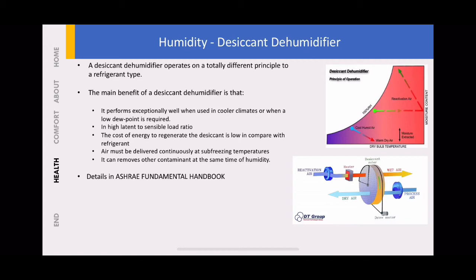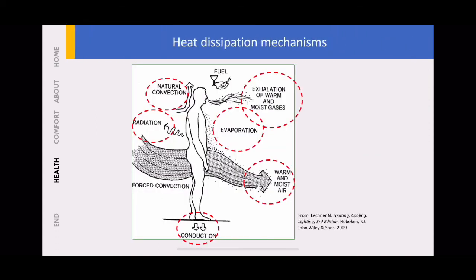Okay, so the graph doesn't really match. Right from here, you increase it, and then you reduce it, but you increase the humidity as well because you absorb. So this part is the absorption. So the cool humid air will become warm and dry air as you use this in the cold climate spaces.